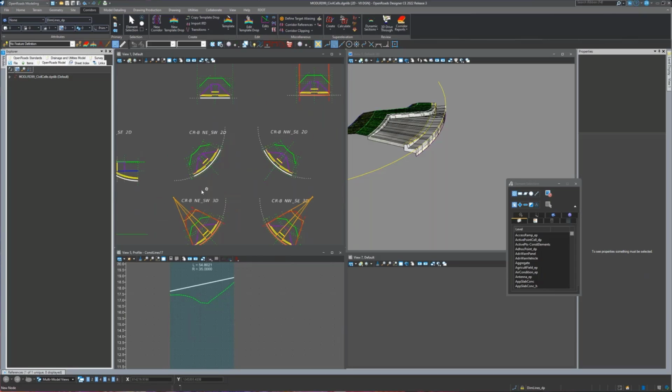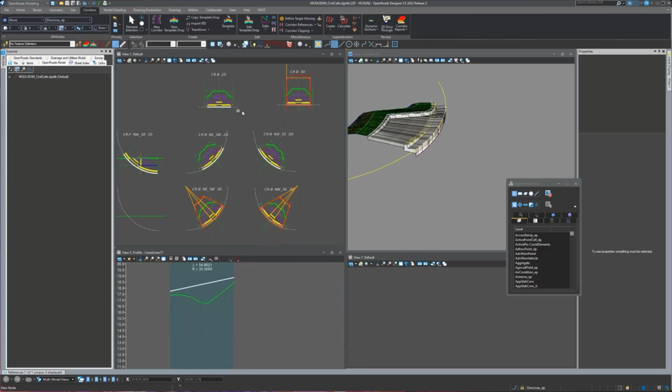And for curb ramps, you'll notice that I did draw them on a curve because that's kind of important. They're curb ramps, I'm sorry, I said curve. But most of the time we're placing curb ramps on a curve, so you would ideally make your civil cell on a curve. Now I've built one up here that's on a tangent. I talked about that too. Sometimes you run into T intersections or you want to do that. So I've got a couple different types.